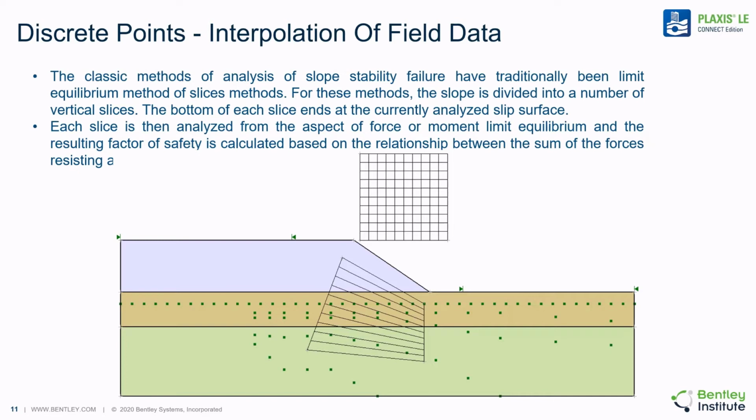It's common in the field to measure the water table with piezometers. Such measurement methods measure a waterhead at a depth and imply a theoretical water table above them. Such measurements, however, do not strictly define a water table. Therefore, it's often optimal to represent piezometric data as a series of discrete points in a model and then interpolate the resulting field of pore water pressures. The interpolation method will project between points and result in a spatially varying water table that is not required to be hydrostatic.